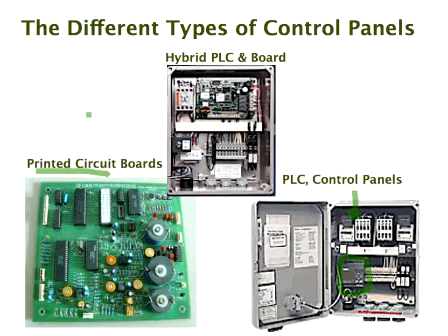The last thing you want to do is open that up and find corrosion and insects and things that have dragged bits of vegetation inside that panel. So just a point from our experience is that, particularly if it's a built-in-place panel, make sure that the thing is located somewhere that it's going to be fairly weatherproof.